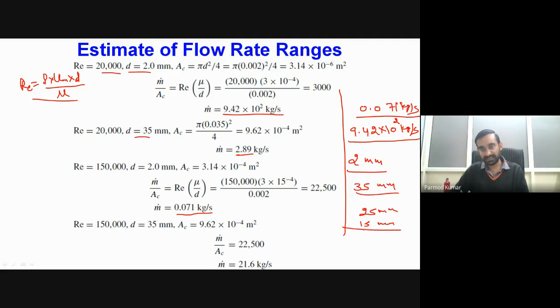Okay, so considering that situation, I am now freezing the tube diameter to 12 mm. One more thing, why I have taken 12 mm is that it is commercially easily available. When we are purchasing tubes in the market, we have tubes of 1 inch, half inch. So as per the standard availability of tubes, we also have 12 mm diameter tubes. So based on that, I have now frozen the diameter of the pipe.